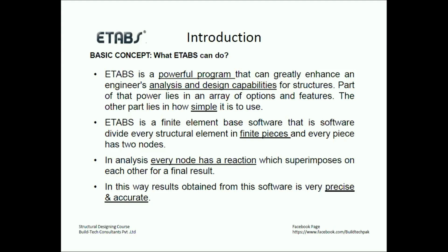You should know the background, what kind of formulas are being used to calculate these things, how the responses have been calculated, what kind of inputs, and in what format the input should be given. Because if you give the inputs in a wrong format, you will get wrong outputs. So whatever software you are using, make sure you know some things manually. Okay, like if there is a beam column with a fixed connection at both ends, you should know what kind of bending moment diagram it should have.